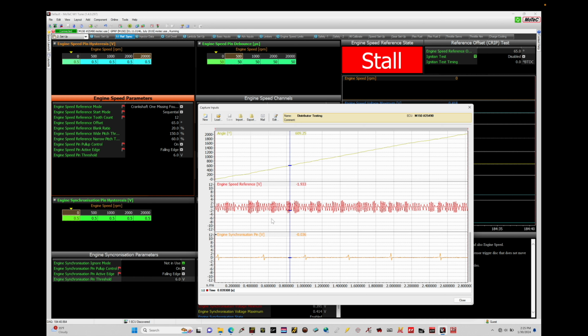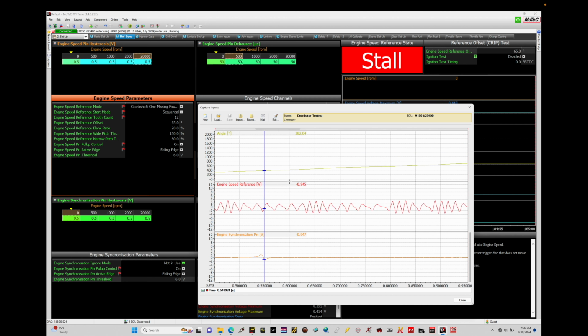That's because I was generating that and simulating it. Typically with a Hall effect, you're going to find a 0 to 5 volt pulse. It's pretty standard. Now when we're talking about a reluctor sensor for both our cam and crank, we're going to notice that we have a completely different type of look to the output, and this is going to be a sinusoidal wave. If we go in here, let's use our up arrow, and we can focus in here a little bit.